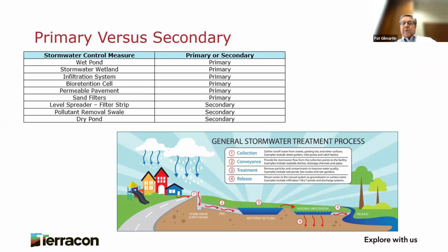When a site has numerous physical constraints and the regulatory requirements are stringent, it can be especially challenging to find an appropriate stormwater control measure. In this case, it may be necessary to modify the stormwater control measure design for the site characteristics, or to provide a combination of them that are suitable in series, such as that sketch shows, where there's an initial wet pond holding the water, or a wet basin holding the water, and then an infiltration basin after that.